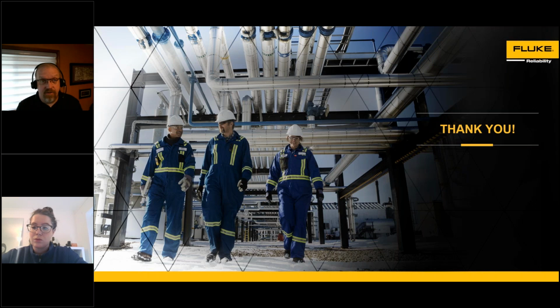That vibration data collection tool can collect, in some cases, just as fast as it can, but that doesn't necessarily mean it needs to save that data. By setting alarms on those overalls, once it surpasses an alarm, it'll collect full spectrum data then. And then at a set interval, whether it be 1 minute, 1 hour, 1 day, depending on what your data storage parameters are, it'll collect full spectrum data across all the channels.